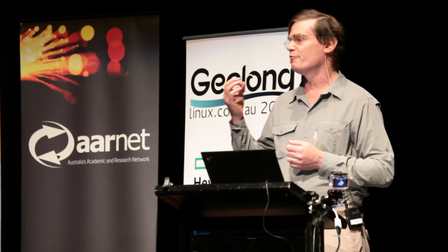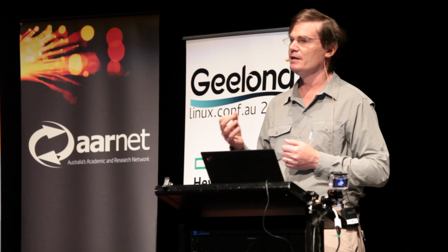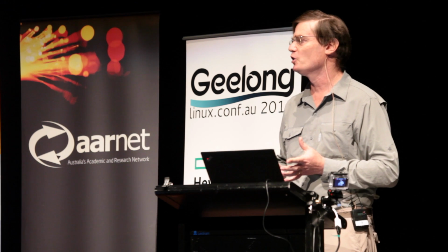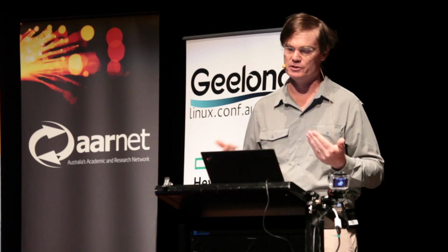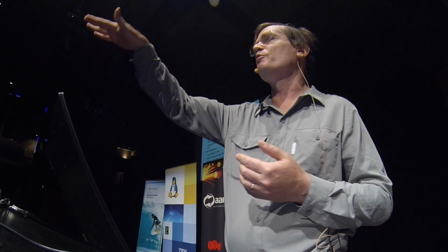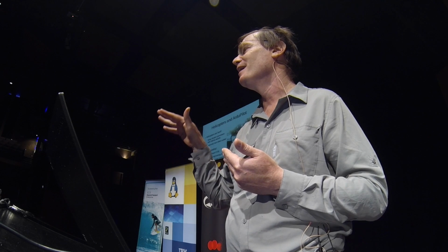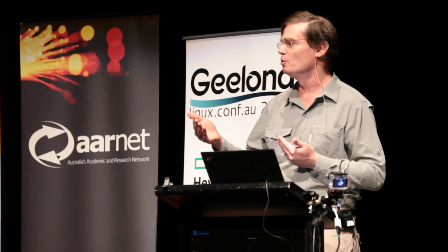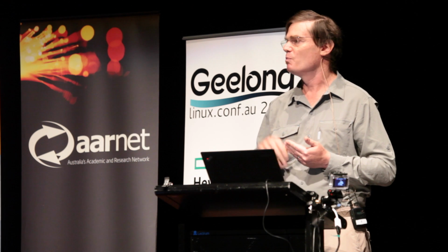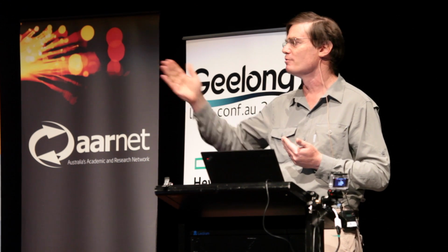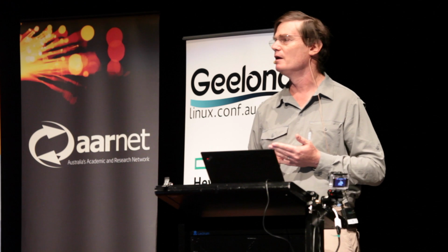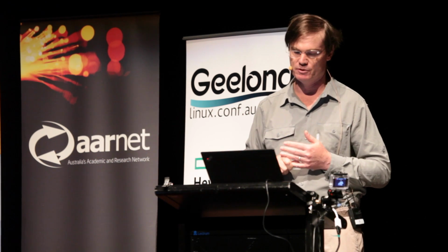They are extremely efficient at VTOL, and basically it's the large disk area. Larger propellers are more efficient, and helicopters have the biggest propellers, right? Enormous propellers. That gains an awful lot in efficiency. And once they're in fast forward flight, they have this interesting property where their efficiency can actually increase as they speed up. Hovering is actually harder for a helicopter and can use more fuel than moderate forward flight. Eventually drag catches up with you in really fast forward flight, and the efficiency drops again. But it's a much flatter curve than most other types of aircraft.